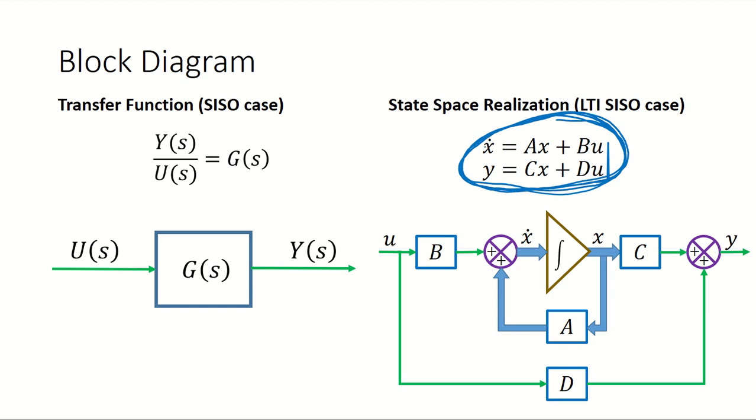So as soon as we have included a dynamics x dot, we have to include the integrator, because only an integrator will give us a scope to create the x dot at the input side of the integrator. At the output of the integrator, we consider the state x. So this is also important. This is a general thing actually.